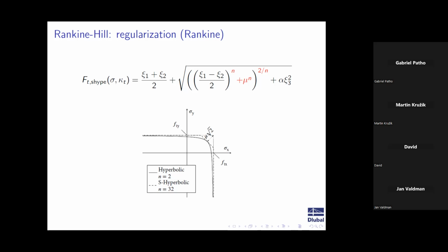My compromise, what I didn't make, is this distance. This is mu times square root of 2. So actually, in this 2 mu by 2 mu square, I'm not really following my initial hypothesis that for uniaxial loading, I get uniaxial response, because here my return mapping will give plastic strains in the other direction as well.